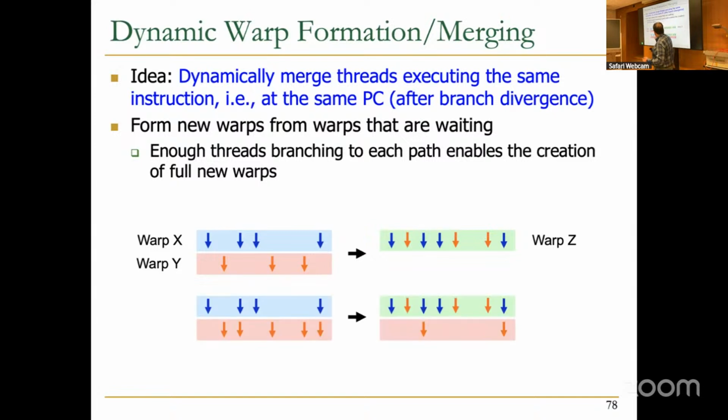But in another example, at some point, you can see that you couldn't combine them nicely together. Why is that? Because some of the threads that were active were actually on the same lane, and in that case you cannot easily combine. Because the register file access, again, in order to be simple, your thread ID specifies on which register you're getting your data.